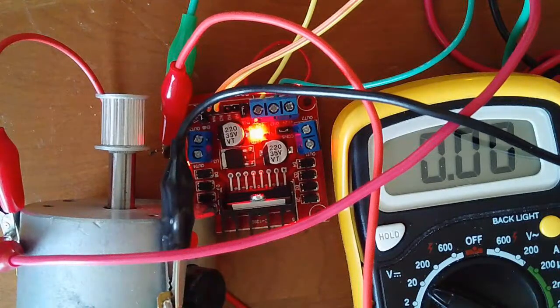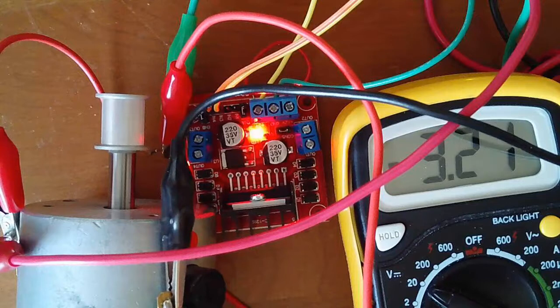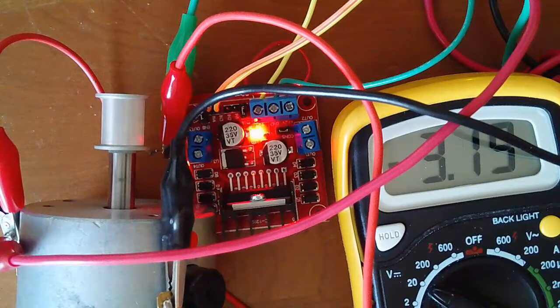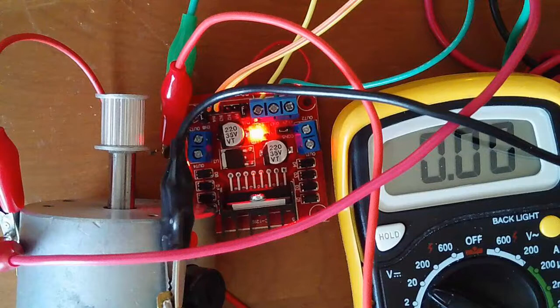Now with a transistor switch, I could turn the motor on or off. With an H-bridge, I can do more. Here I actually have 3 different modes. It's spinning clockwise when applying plus 3.2 volts across it, counterclockwise with minus 3.2 volts, and off with 0 volts across it. So you actually have those 3 states. Forward, stop, reverse. That's what an H-bridge can do.